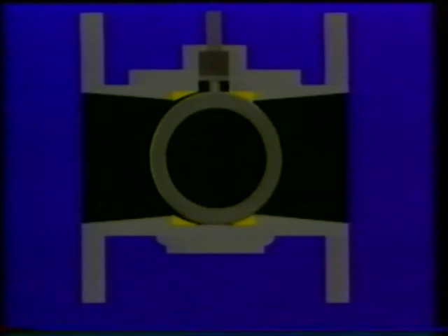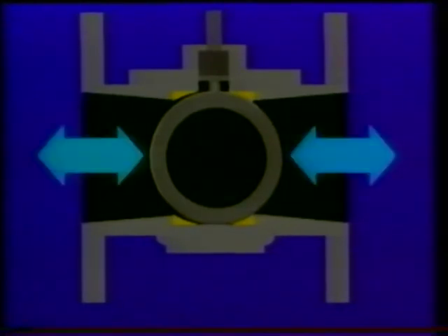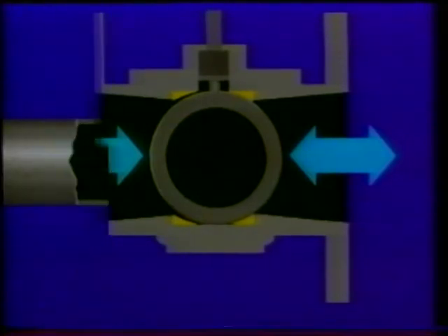The seal materials used, as well as the process fluid, can have a great effect on the severity of this friction. In other valves, like a butterfly valve, this friction may only exist when the valve is closed or partially closed. The torque required to overcome this friction is often referred to as breakaway or breakout torque. Additional static forces affecting rotary valves are presented in your text.